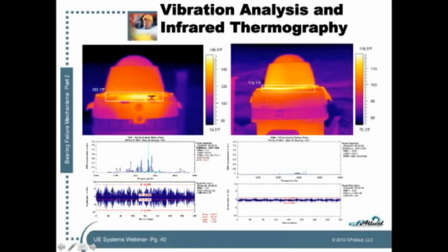looks like. So we know that when the bearing defect gets to about 16 Gs or so, which is pretty severe for that type of bearing, pretty severe for almost all types of bearings, and we know it's the stationary race, we can look up here and we can see the corresponding thermal energy or thermal data that goes with that bearing signature.